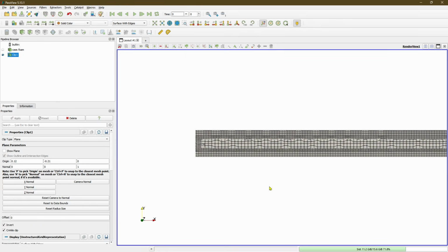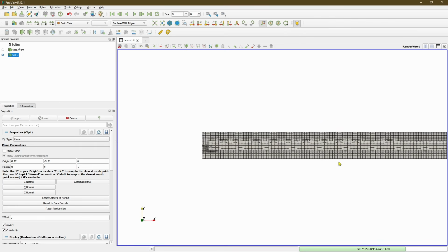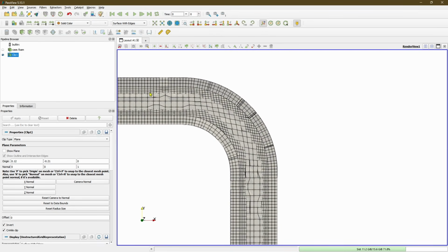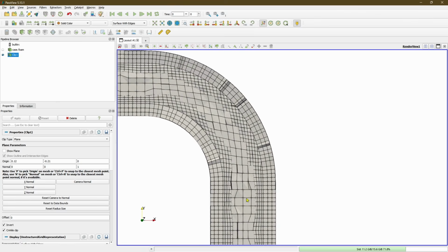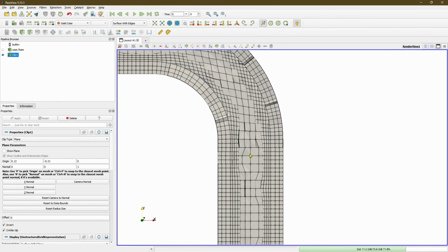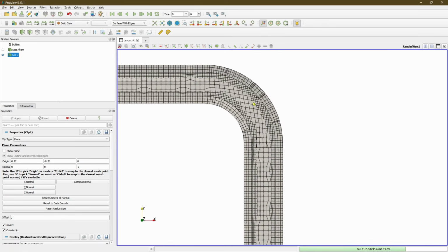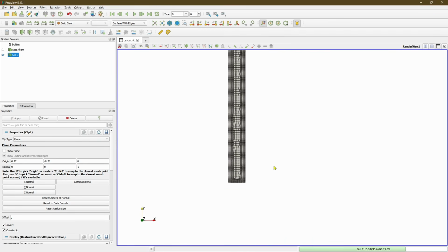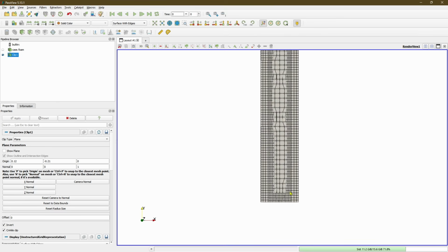So we can see that now the mesh looks much more uniform across the board. Even though in the center line, we can see that the cell size is a little higher. That's fine. We expect more turbulence to come around these walls and move away from the walls and then just slosh around somewhere around this region. So we'll just run the simulation and understand what this looks like with the results.